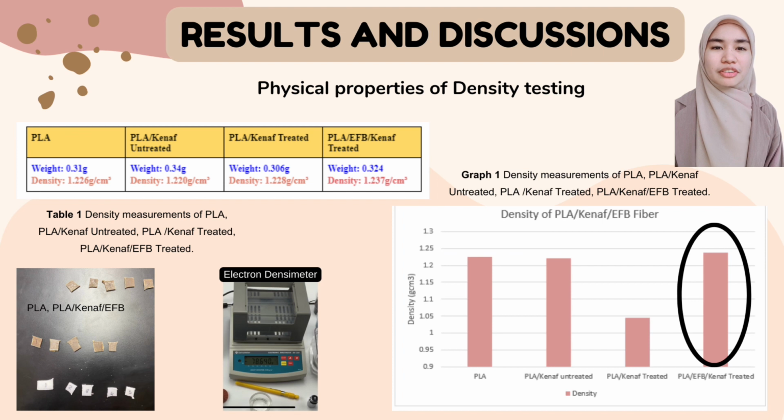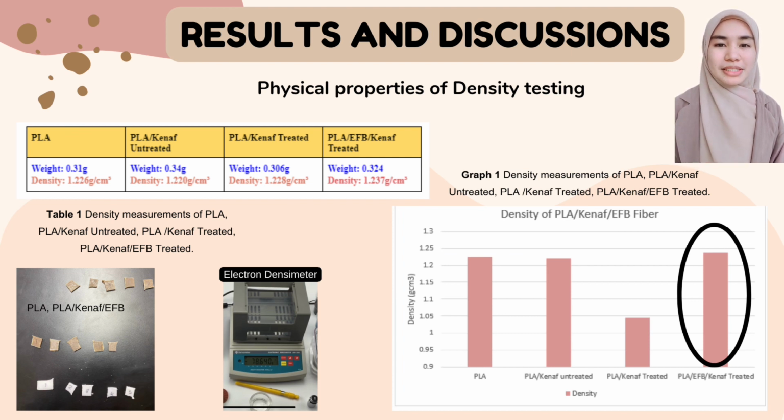Generally, the introduction of filler affects the density and free volume of the polymer chain. Free volume can be increased by the combination of decreased molecular weight and increased chain mobility. Therefore, increased filler concentration increased free volume, hence leading to the density reduction visible in graph 1. Low density leads to a lighter weight composite.